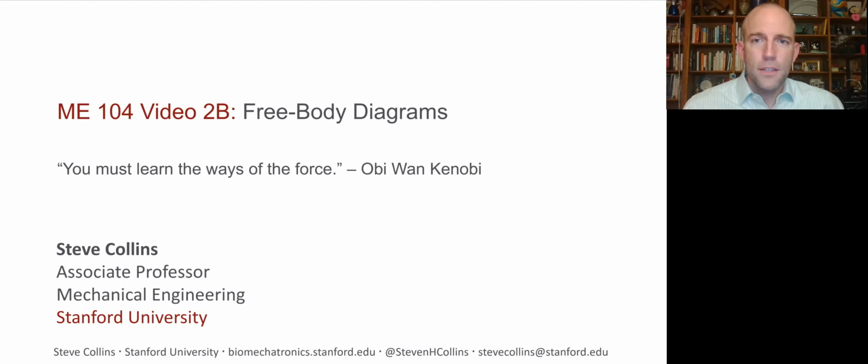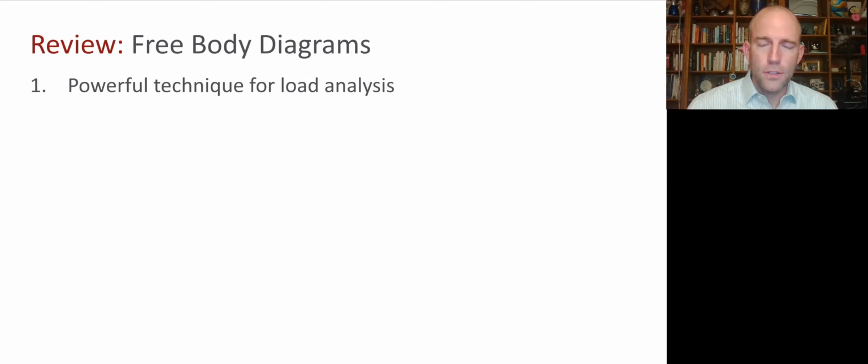So free body diagrams. This is a powerful tool for load analysis in mechanical systems design. It's very, very important to know how your system and all the components in it will be loaded, right? Big forces can cause things to break. Forces on moving parts can dissipate energy, and you generally need to know the forces and moments on things before you can move on to stress analysis or FEA.